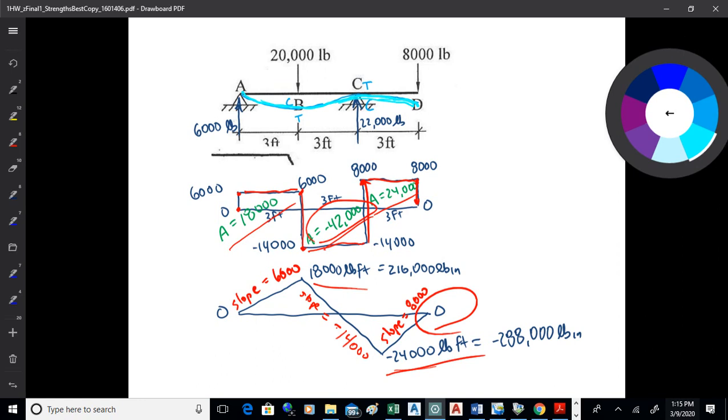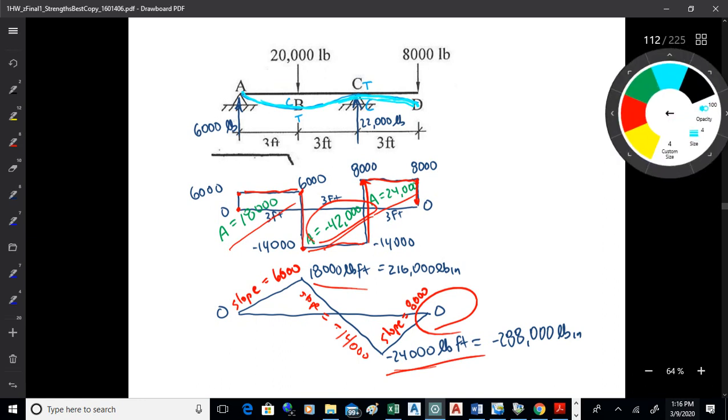So that does introduce a little extra work to be done here, because we've got a positive moment value there, but then we go to a negative moment value as the beam bends down. So the moment shifts from positive to negative on that beam, okay? Now I get pound feet out of that, but I want to convert to pound inches because my beam dimensions are inches. So I want to get into that unit system. So we good with the moment diagram?